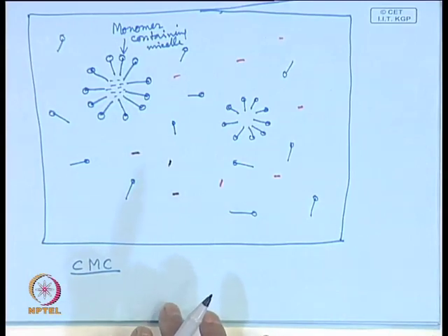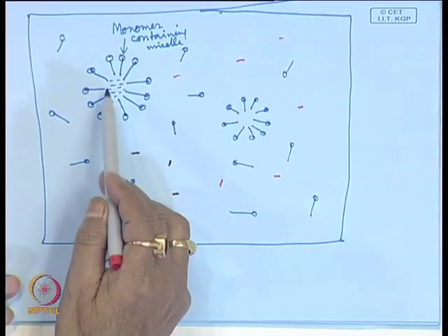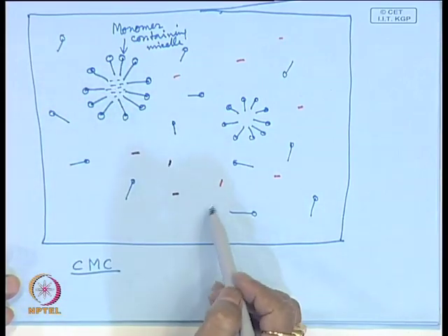That solubility may be 1% or less than 1%, or it can be more than 1%, also 2 to 3% or 4% solubility of monomer in the aqueous phase. So, after adding monomer, we will get monomer in two phases: in the organic phase within the micelle, and in the aqueous phase in dissolved condition.